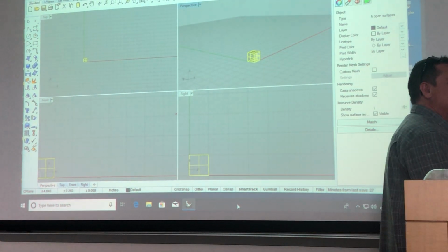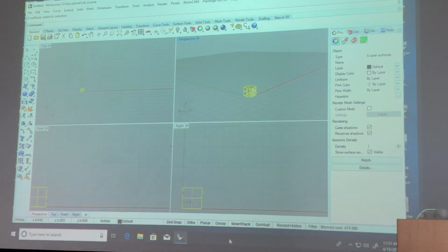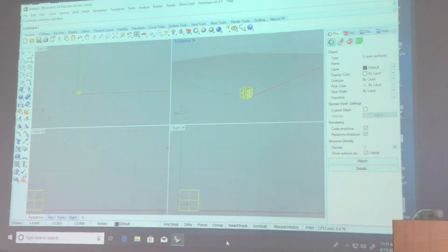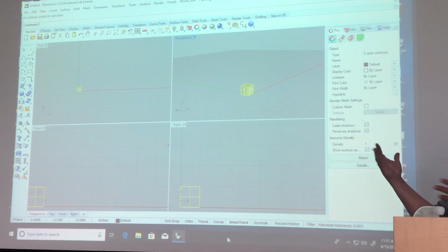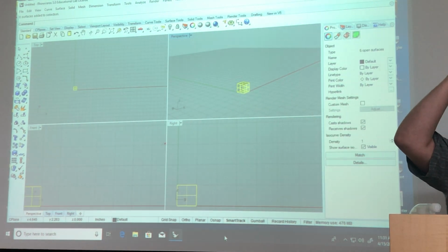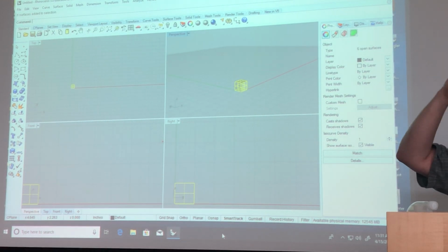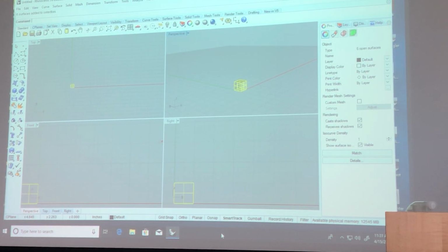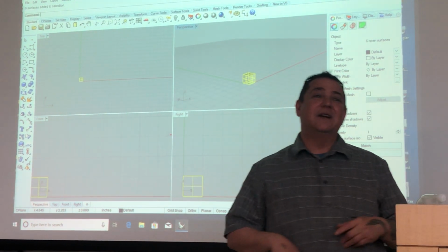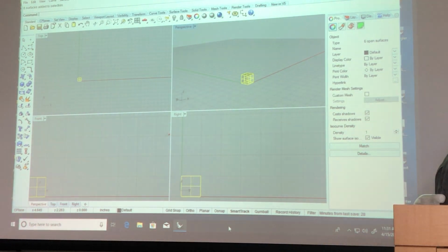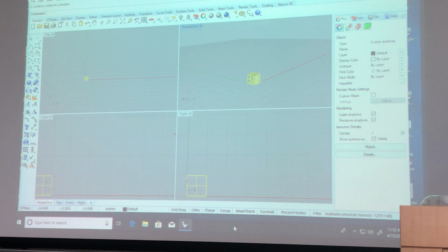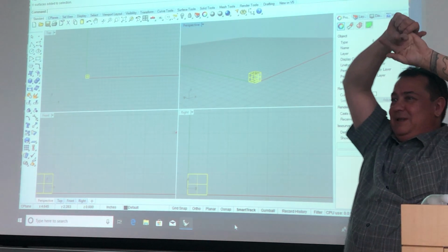In order to make a reservation, you're going to need to come down to the Bear Lab and process your STL in MakerBot Print. MakerBot Print, I'm going to show you really quickly in a second, is the software that takes this file and turns it into a printable object. Not fix your model. What the 3D printers actually read are individual layers. So there's another piece of software your STL file has to go through to make a MakerBot file. The MakerBot file gets loaded into the MakerBot. So: model in Rhino, export as STL, import into MakerBot Print, process for printing.